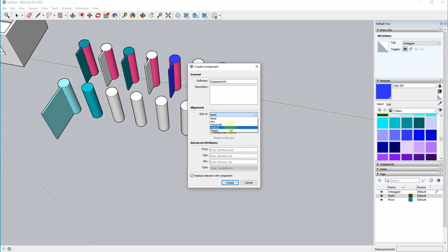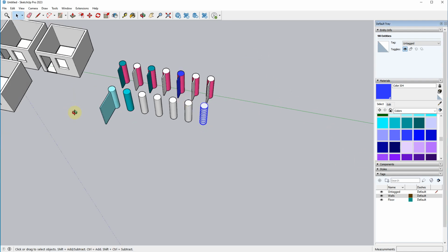Occasionally you will start working or you will import something like a light sconce, for example, and it's not going to show up in every situation, because someone actually came in here and set this to glue to vertical. So if you were to use that, it would only apply to a vertical space versus a horizontal. It's usually an issue we see with lighting because people set it on some of those things. We typically don't see it in anything else. So, again, one of those things to watch out for when you are bringing stuff in from the 3D Warehouse.